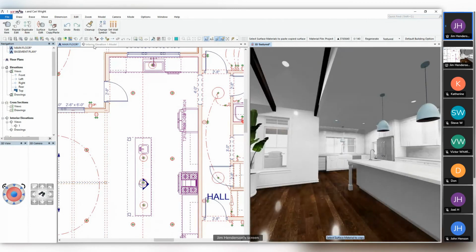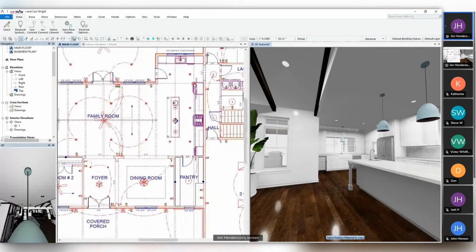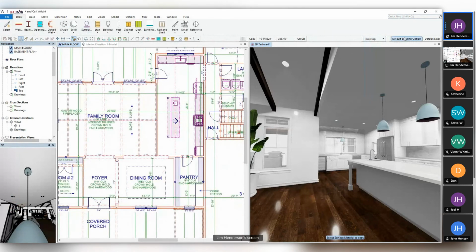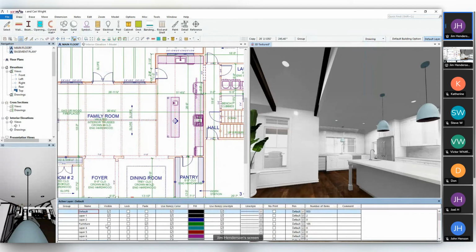Things like stools and such, right? So that's just furniture that we're going to add in here to specify that out. So I'll do that inside my drawing mode. And in a lot of cases, this is where you come in through layer, and you may have a furniture layer, right? So what you see, I just turned this on and I can see the furniture. Okay, it's actually being set to fade, right? And when I turn it off, it no longer prints on my construction drawings. So again, entirely up to you, but that's going to be the layer that I'm drawing in.